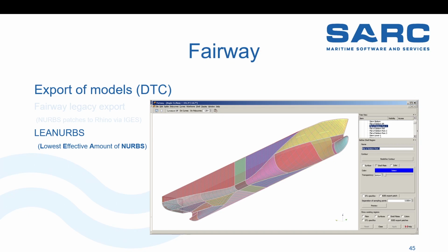So you need to define this in four-sided patches. Actually, this looks like a three-sided patch, but that's because we define an additional point here or there along this route somewhere, so that it will be four-sided. You can just pick a point on any of the curves, and if you do that sensibly, you'll have a nice output. Yeah?